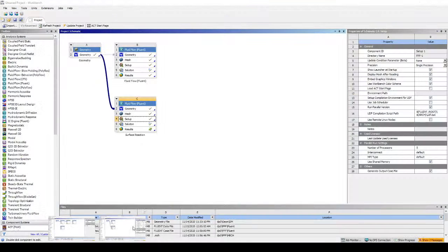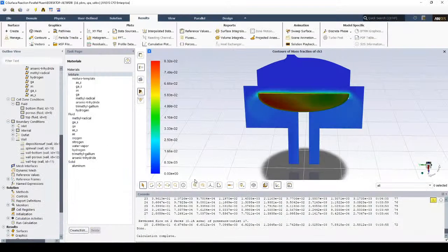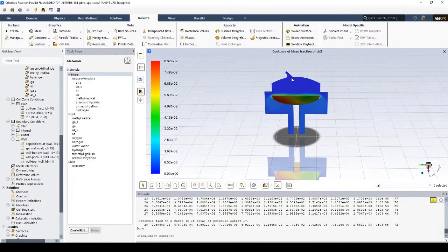The last thing I wanted to show was, we've looked at so far, our simulation can potentially adjust different amounts of flow into the system. We can adjust the temperature, rotational velocity. We can even adjust some of the chemistry information. But oftentimes people want to operate these things not as a continuous deposition, but in bursts.